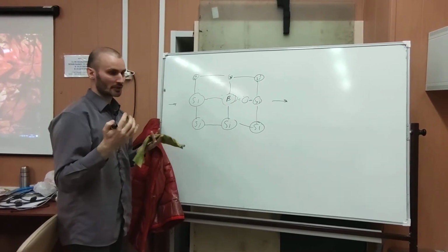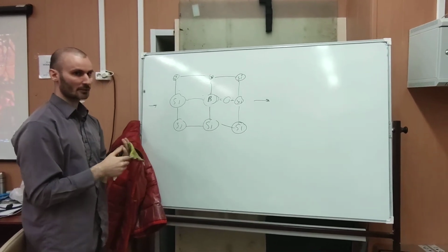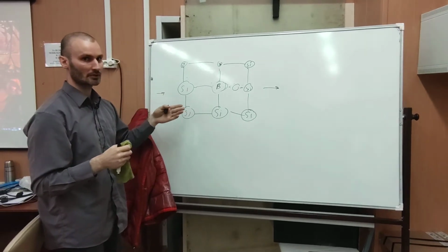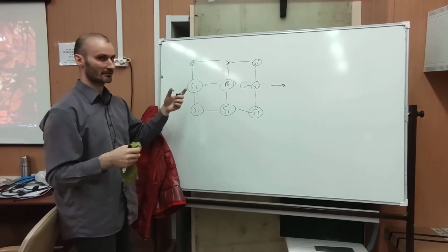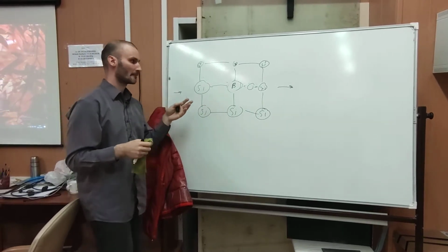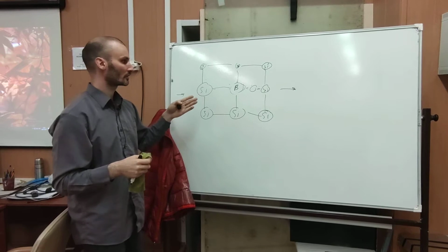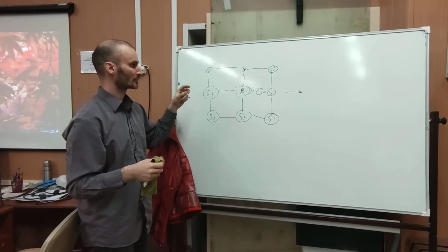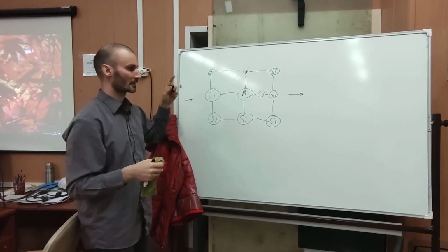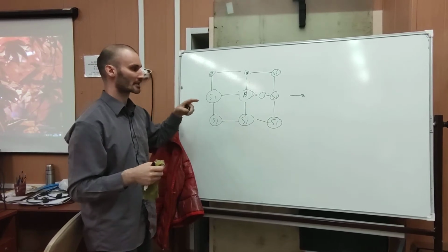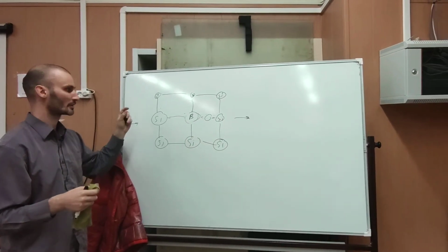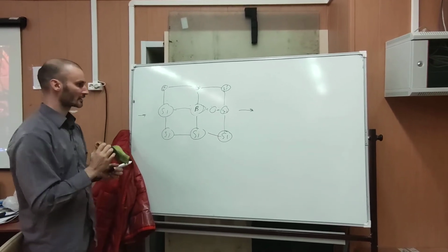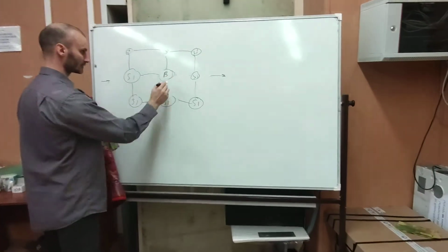So we can heat the material to make it conduct. We can emit light on it to make it conduct. We can add n-type doping, which is phosphorus, for example, which has excessive electrons that make it conduct. Sorry, I said p-type before, but that was n-type doping. Or we can add p-type doping like boron, which doesn't have enough electrons, which has fewer valence electrons than, for example, silicon. So we have holes, and that way we have conductance through holes. Okay, so this is the complete set of ways of making a semiconductor conduct.